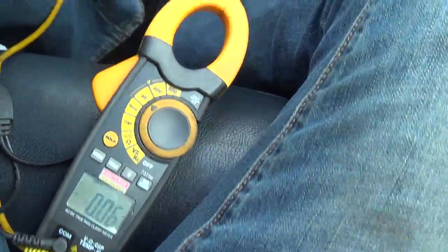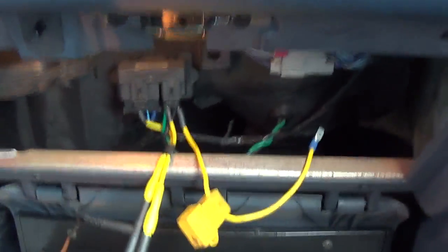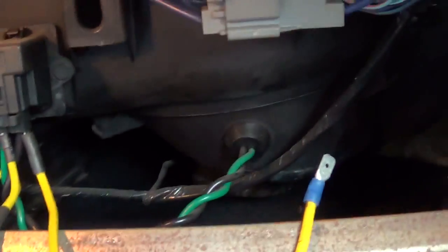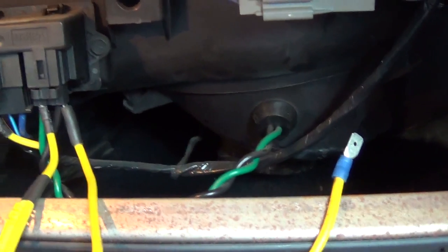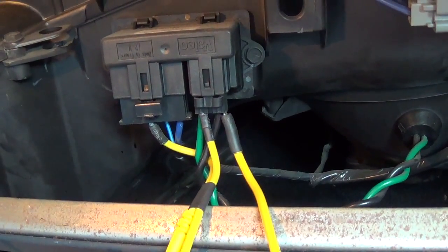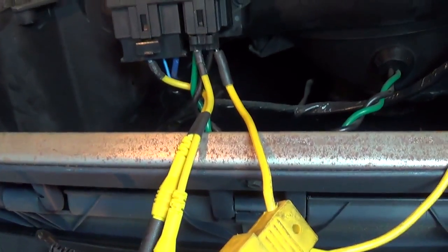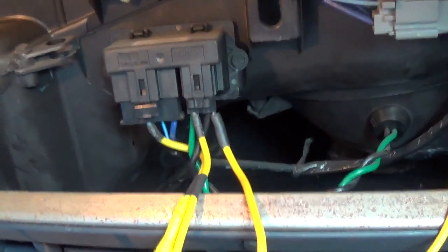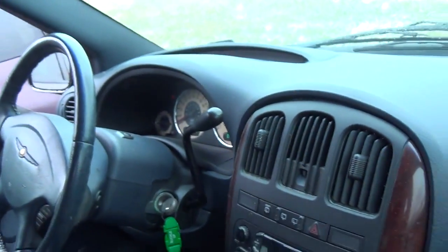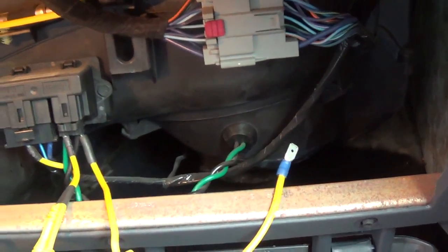So that is why you do an amp check on your blower motor. So basically, if the blower motor is drawing too much current, we're going to fry our module. And if we replace the module, it'll work for a while, but it will die prematurely. So I can give this lady a quote on just the module. And this is kind of an old van. She's just keeping it going for a little while. So if she wants to fix it right, we're going to have to get a new blower motor as well. There's no way around it.